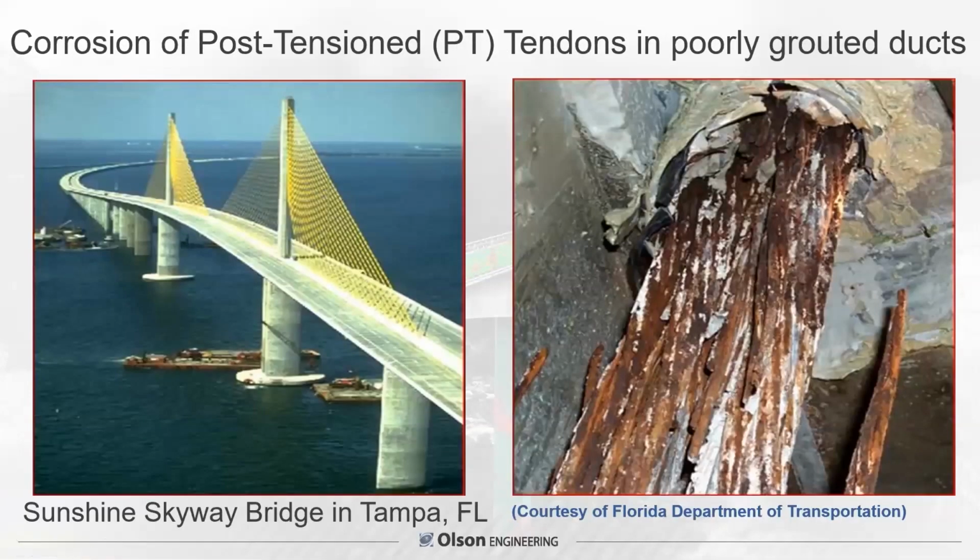So shifting gears a bit, one of the common problems in post-tension bridges and post-tension construction is certainly corrosion of the tendon cables or wire strands that make up the post-tensioning. Grouting has been greatly improved, and this is less of a concern than it used to be, but if things are not well grouted, this is the Sunshine Skyway Bridge in Tampa, Florida. Those big piers were not well grouted. It was poorly grouted, and in the saltwater environment, with the heat, severe corrosion occurred.